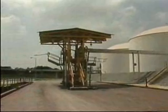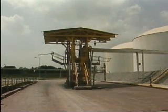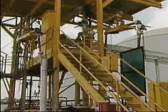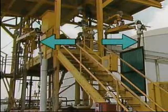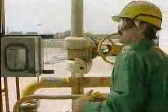Transfers involving tank trucks are normally made at loading racks. A tank truck loading rack is basically one or more freestanding structures called islands. An island typically has loading arms on both sides so that a tank truck can load from either side. Each loading arm typically has its own meters, gauges, and piping.